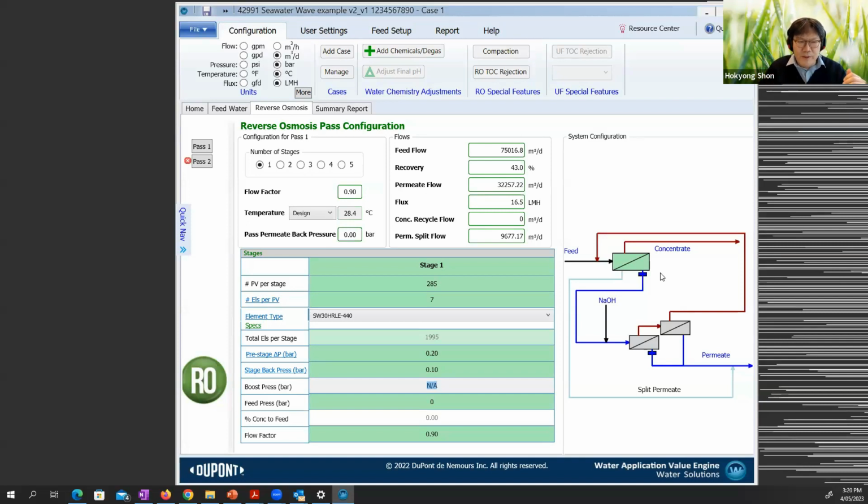That's the reason why you want to slow down your permeate. So in this case, you can utilize the back pressure a little bit, which will balance your concentrate flow going to the next step, and then the next concentrate channel. So that's the reason why you are putting this one. Otherwise, you can remove your back pressure.